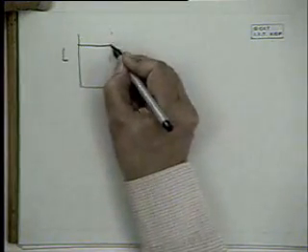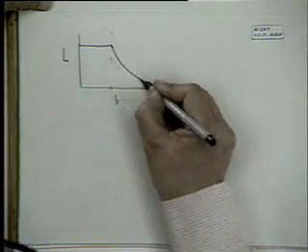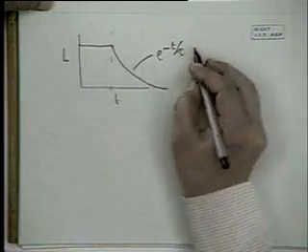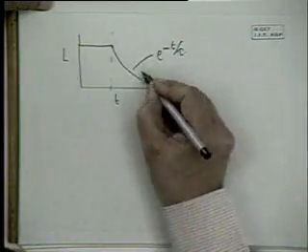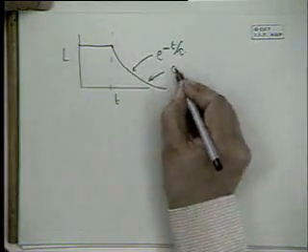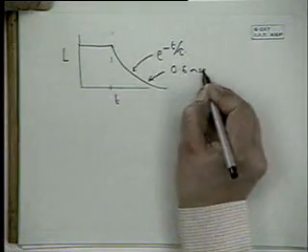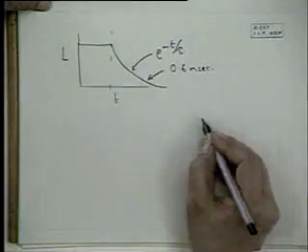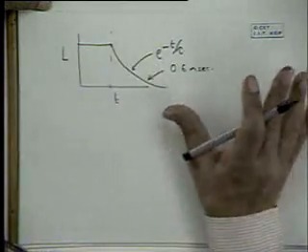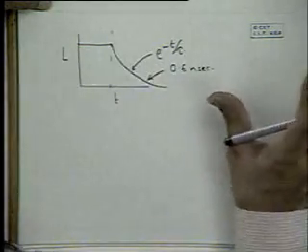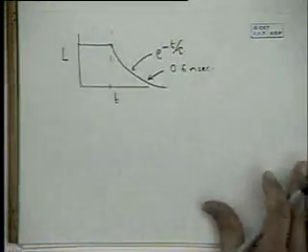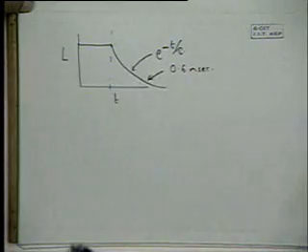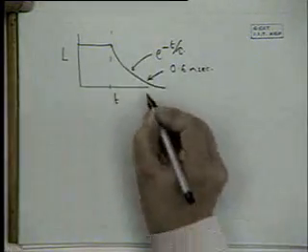Then the light intensity from the gallium arsenide will decay like that, as e to the power minus t by tau, where this decay time will be of the order of 0.6 nanoseconds. So one can actually measure this. This is assuming that the surface recombination is not very fast, and it does not have a lot of non-radiative recombination centers and other defects.